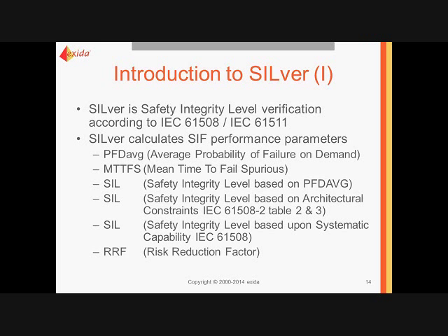So if you said, all right, I need a SIL 1, but it has to be with a risk reduction factor of 65, that is far more precise, and the designer has to show that he's met that risk reduction factor. If not, as we were saying in last week's webinar, you need to err on the side of conservatism.